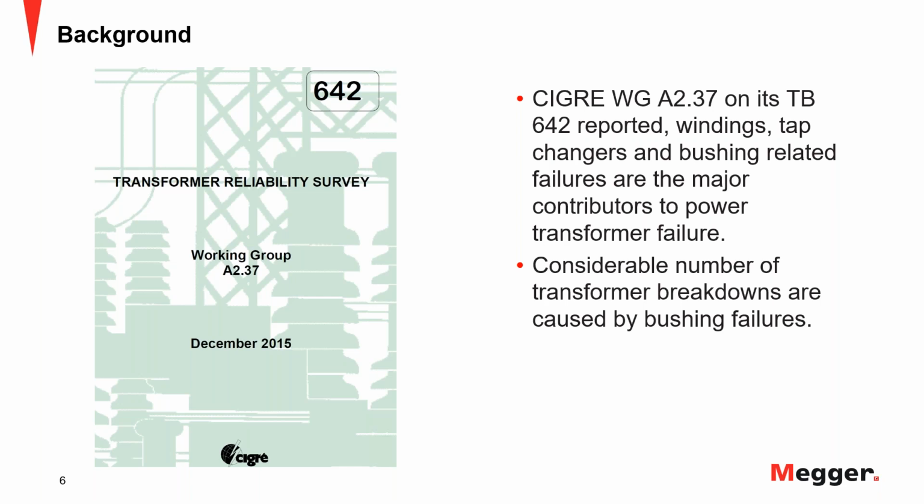You can see in this report that a big number of transformer breakdowns were caused by bushing failures. So it's not always the transformer itself or its internal components in the coil winding core assembly, but it could be some of the accessories that we have for it, in this case the bushings, that may act as part of it.